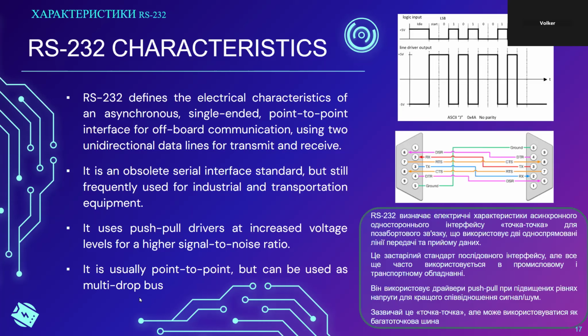This has the effect that if you are working with an actual RS-232 interface, and lots of industrial devices still use actual RS-232 interfaces, they can be detected by the standard 9-pin D-sub connectors. If you take a multimeter and measure the voltage between ground and pins 2 and 3, the one with the negative voltage in idle mode will be the transmit line at that device. It's just a quick check, if one wasn't sure which pin is the transmit line.